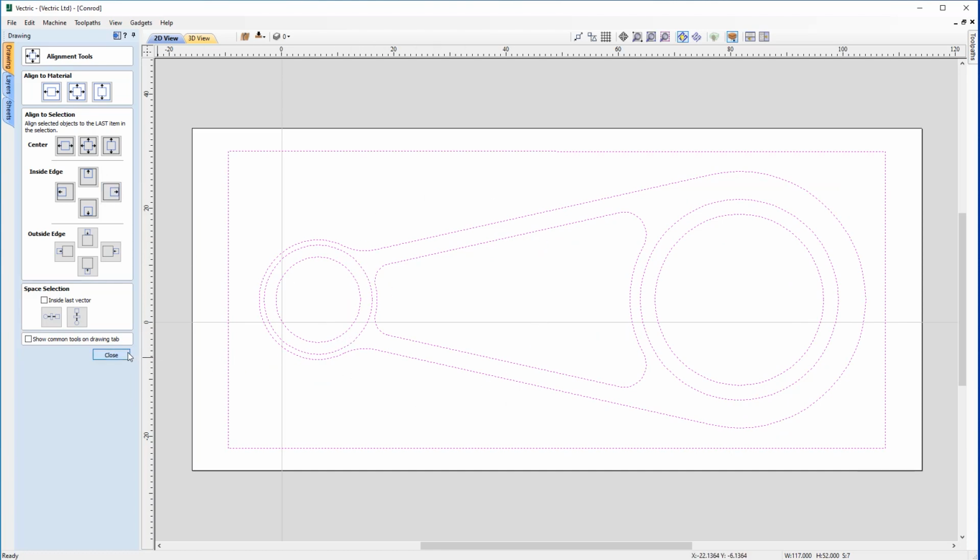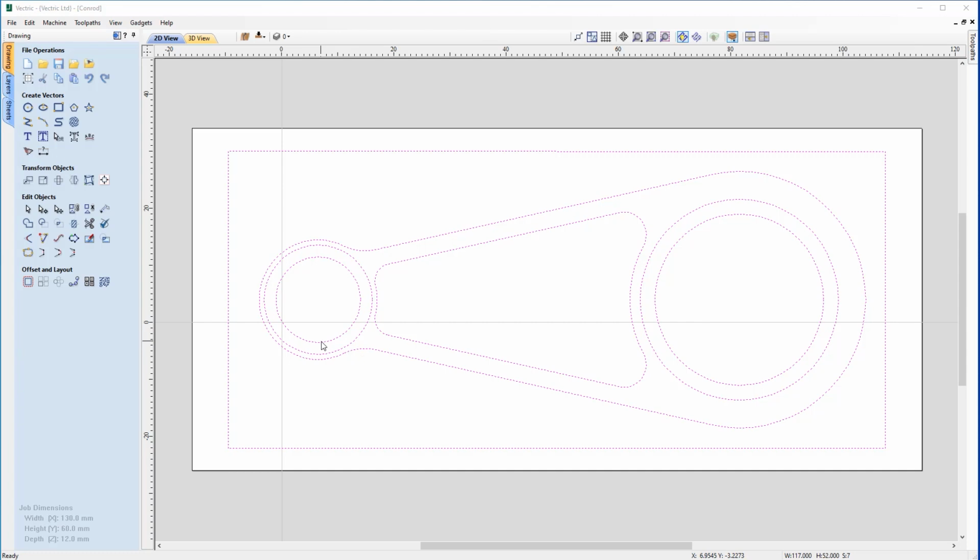That looks great. Okay, so right away you can see that there's a problem, which is that the XY datum is no longer in the middle of our small circle here. So we need to fix that. And there is a couple different methodologies you can use to do that. But one way we're going to look at is actually by looking to correct it, by looking at the offset from down here to here and adjust that into our XY datum offset to get it to the right position.